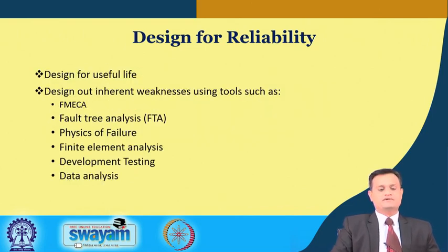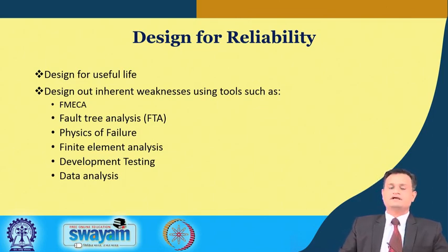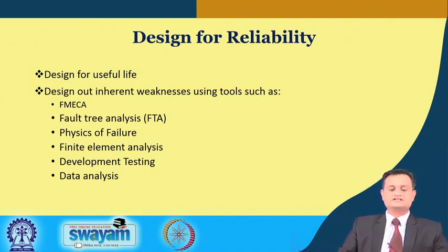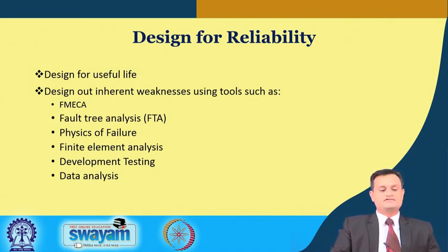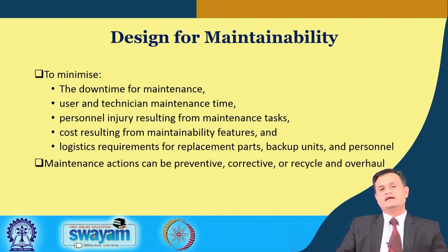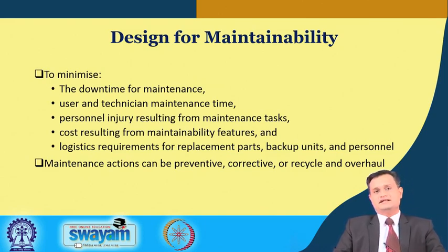So you have design for reliability and various tools: FMEA or FMECA, there are different variants available, fault tree analysis, physics of failure study, where you can study stress, strain and other phenomena, finite element analysis, development testing, and data analysis. Another important X in DFX is maintainability.